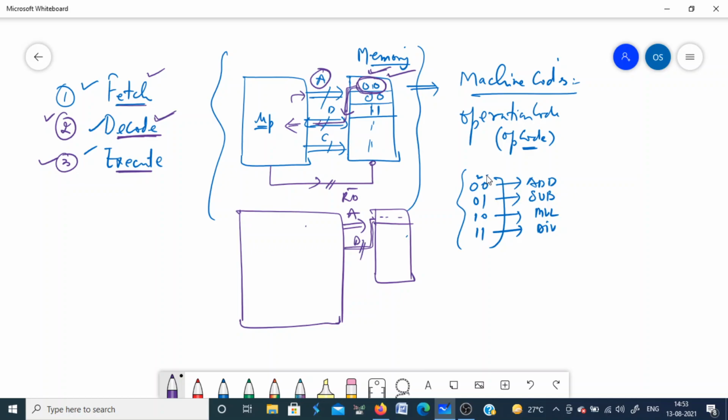It basically goes to a special register which is called an instruction register. We will come to this later when we discuss the architecture of the processor. So this instruction goes inside the instruction register first. This is the fetch part. You place the address on the address bus, the location is identified, the data is placed on the data bus, it comes inside the processor into the instruction register, and then you have an instruction decoder, ID. This instruction decoder will decode the meaning of this instruction.